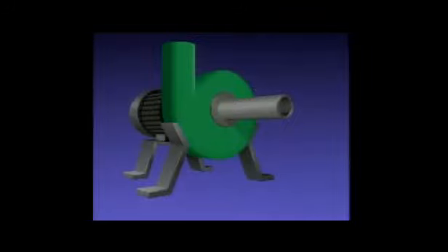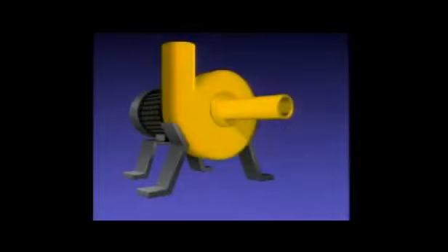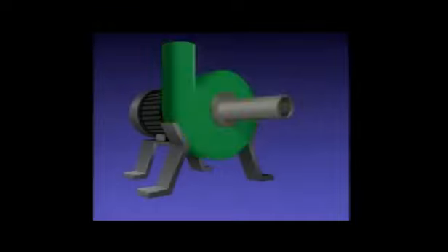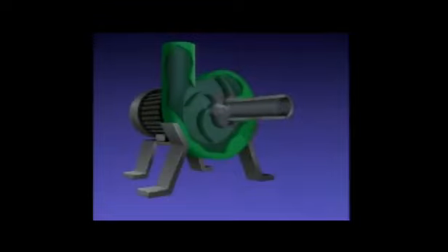The purpose of the pump's casing is to contain the liquid inside the pump during operation. The casing houses all of the pump's internal parts. The liquid leaves the pump through the outlet. This side of the pump is also called the discharge side. The pressure of the liquid is highest at this point. Inside the pump, there's a component that physically moves the liquid through the pump. The type of component that's used determines the type of pump.